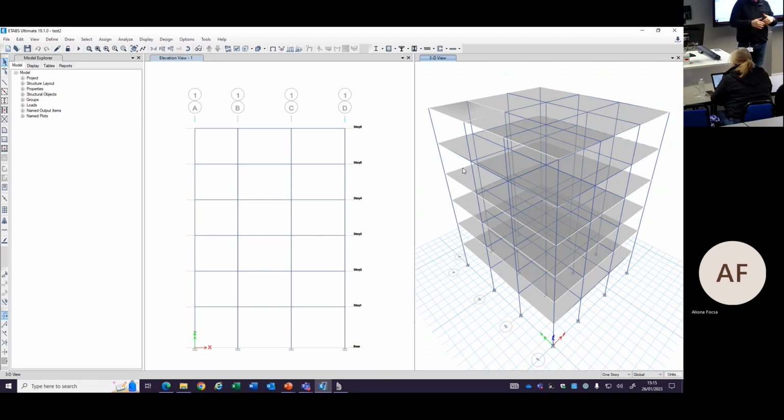Okay? So designing for different things. You can assume that there are many things different from concrete. They are totally different types of structure. So the beams and columns need to be designed again for the axial forces, shear forces, and bending moments, but in a different way from concrete. The uncertainties in steel structures are less than concrete. You can imagine, the more advanced material you have, the less uncertainty you have. Steel is far more predictable than concrete in terms of material.